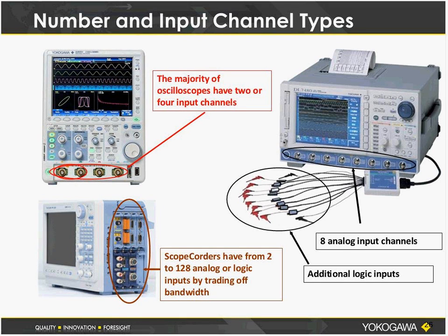All right, another key differentiator here with oscilloscopes is input channel types. And you'll usually know how many channels you need to measure. The vast majority of the time, you'll see 2 and 4 channel models. And if you need to work on 1 through 4 types of inputs simultaneously, you have a lot of choices available to you. At the same time, we do realize a lot of people these days are working on 3-phase measurements with inverters, with appliances, with motors, with electric vehicles, and so on.